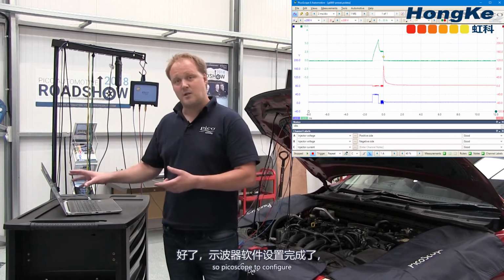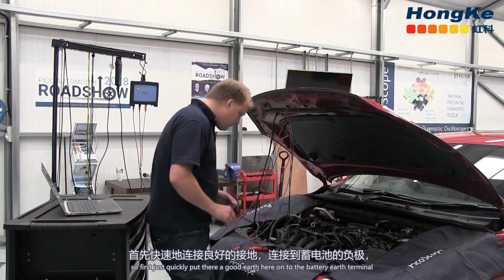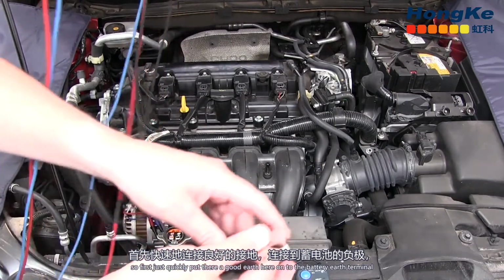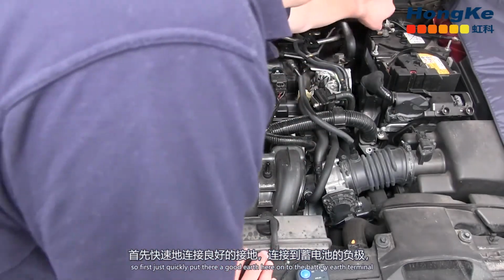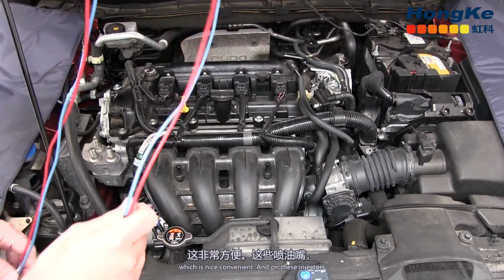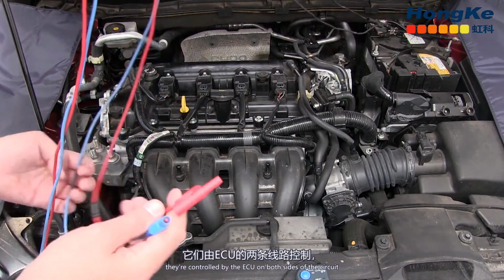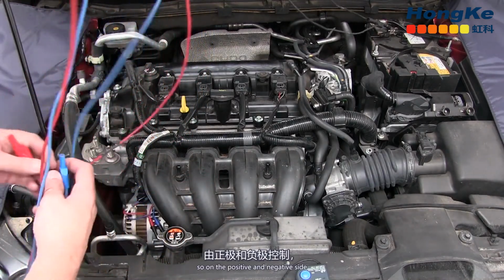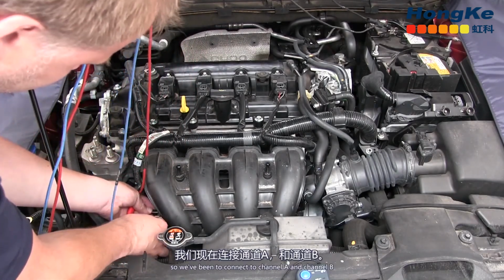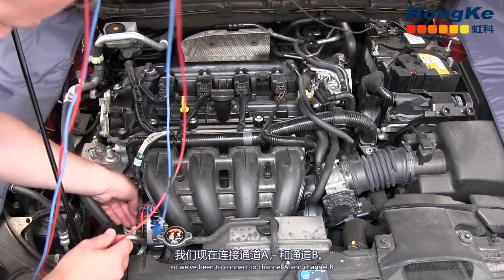So, Picoscope's configured, and the next thing we need to do is to connect it up. First, we'll just quickly put a good earth here onto the battery earth terminal, which is nice and convenient. Then on these injectors, they're controlled by the ECU on both sides of the circuit, so on the positive and negative side. So we need two voltage probes. So we're going to connect channel A and channel B.